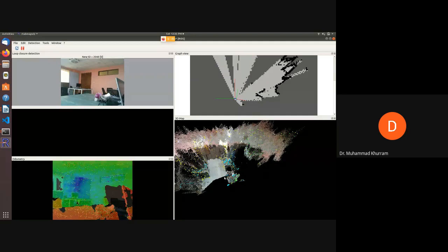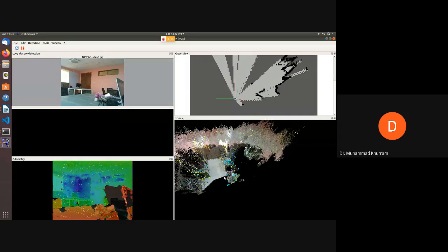Then after the planning module comes the control module. Right now we have just created the plan of what routes we have to follow. The next step is actually following that route and performing the actuation. That's where the vehicle controller module comes in. The vehicle controller module provides the steering information and the velocity control information.